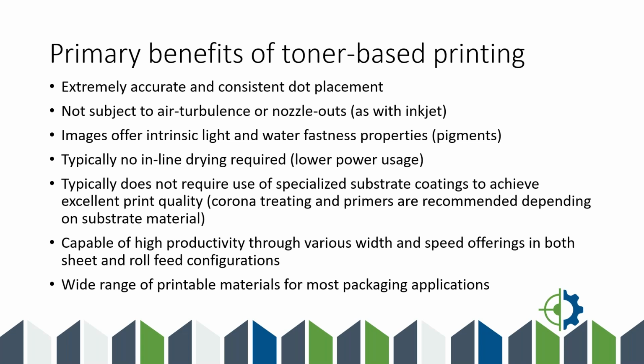And when you get into a broader set of film type products, whether polypropylene, polyethylene, polystyrenes, polyamides, these types of things, you need to maintain the surface energy, and you're going to have to probably put a primer down on that substrate to guarantee and improve maximum adhesion. You don't want that toner flaking off before it's coated or laminated or UV varnished.